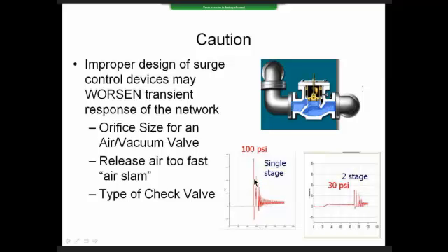Well, if you expel the air through a larger orifice, some of these devices have maybe even a 6-inch orifice that they bring it in and expel it, you can get a pretty big pressure spike. And this is basically the same thing that you would get if you had a cavity collapse. It's due to the water accelerating and impacting on itself and causing a huge pressure spike.